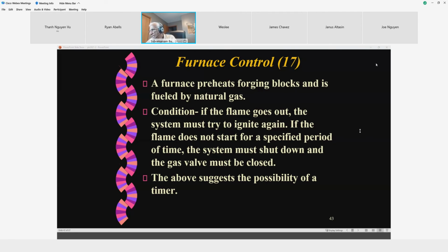Now, when the condenser is heated to a certain level, normally it'll be at room temperature. Now you lift it up because the flame has come on. Only at that time the fan will kick in, because these are all aspects of the high efficiency furnace. It wants not to circulate colder air inside the house prematurely. So when the condenser is heated to the level they have decided as optimal for extracting heat from the condenser, the fan comes on. So it will switch from a slow speed to a higher speed if your furnace is equipped to do it.